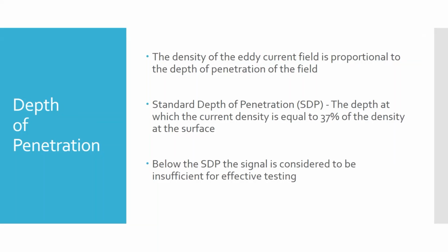Okay, there are 3 levels in non-destructive testing. In each method, you can be certified as a level 1, a level 2, or a level 3. A level 1 is someone who performs the test and can basically get results. If there's interpretation required, you need somebody who's a level 2 that's had additional training and additional time performing the test. And then finally, there's level 3, and level 3 are the people who design the tests. They decide what parameters, what probes to use, what frequencies to set the tester at, what driver power to set it at. And we'll talk about what those different things mean in a little bit.